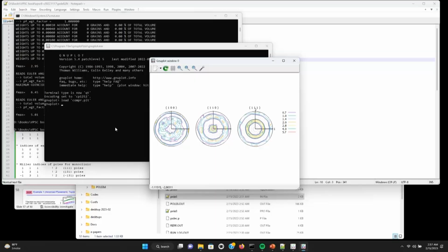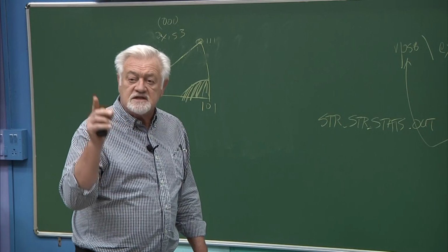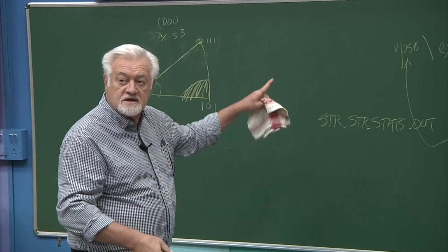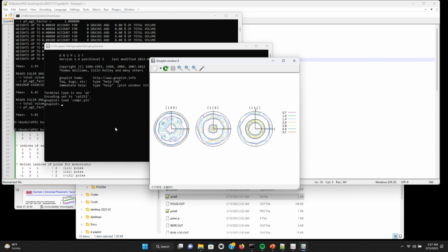Yes, correct. The dots here are the centers of the cells in which I divide the pole figure, and those dots correspond to intervals of 10 degrees. So it's 85, 75, 65, etc., up to the center. You come from 0 towards 90, and they are every 5 degrees, roughly, because it is not exactly a division in angles, but a division in the cosine of the angle.